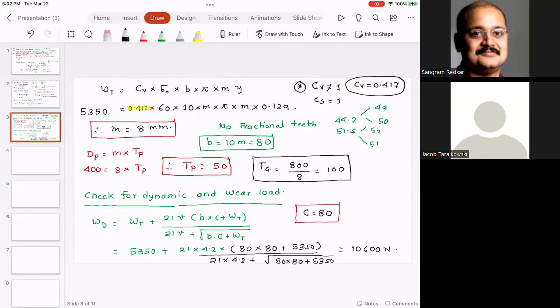Now what it is saying is 20-degree stub. Are you with me so far? Yes. You have cast iron to cast iron 59, steel to cast iron 81, steel to steel 119. Do you agree with me? Yes. Now, here is the issue. In this particular case, we don't know what the material is. So that's why I approximated it to 80.